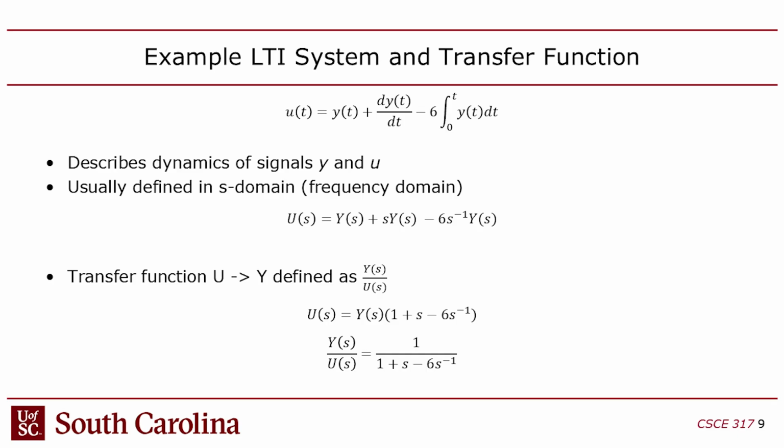And then this is the integral of y dt, right? So all you got to do to get this into the Laplace domain is, this integral, you stick an s in here, and this derivative corresponds to multiplying by s, and this integral corresponds to multiplying by 1 over s, right? s to the negative first power. So now you've got it in the Laplace domain.